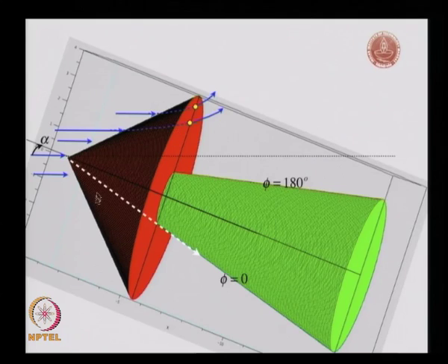Now let us consider one radial line which goes here, and this is the phi here, and what is this S1 now? When we have this flow, the free stream, it comes from here and encounters this part of the shock, the bottom part of the shock, and so we will have the streamlines in this particular case. Since there is no symmetry here, it is not going to spread out nicely, evenly.